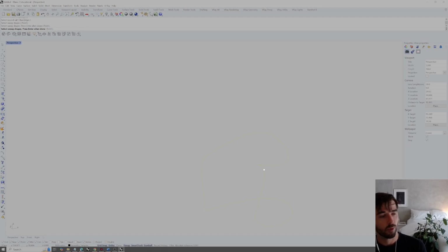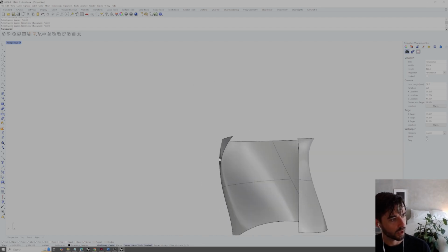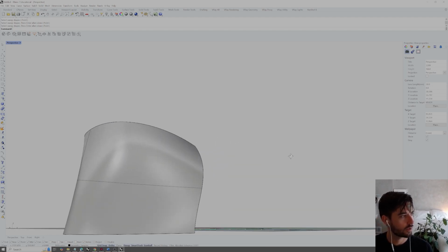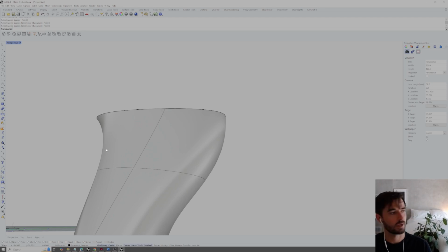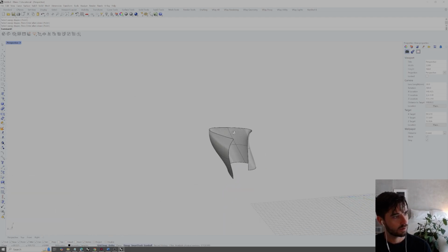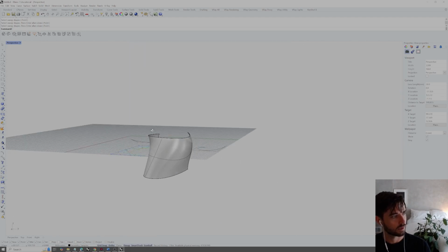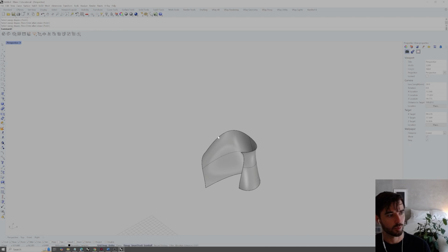It is going to perform the interpolation infinitesimally or mathematically so between these 2 profiles. So if we hit enter, OK, we now get this kind of bellowing out on the start, and then it slowly transitions right about here to this concave inward profile at the end. So you get that smooth transition between not just the two rails, but also the two profiles.